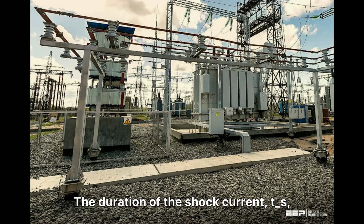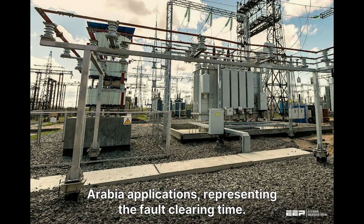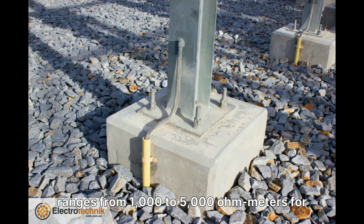The duration of the shock current, T_S, is in seconds and is typically set to 0.5 seconds for National Grid Saudi Arabia applications, representing the fault clearing time. Resistivity of the surfacing material, ρ_S, typically ranges from 1,000 to 5,000 ohm-meters for materials like gravel, while ρ is the resistivity of the soil beneath it.